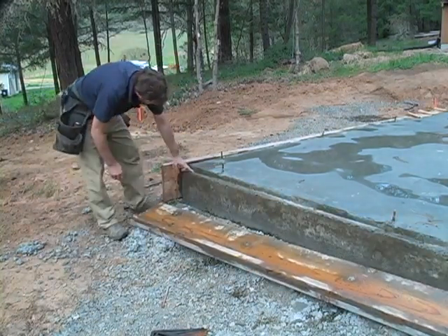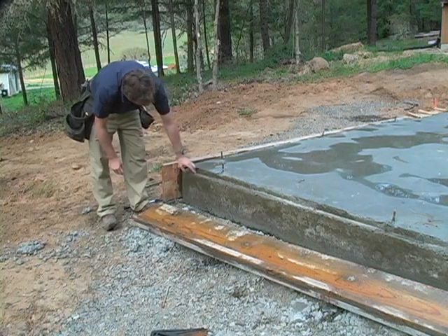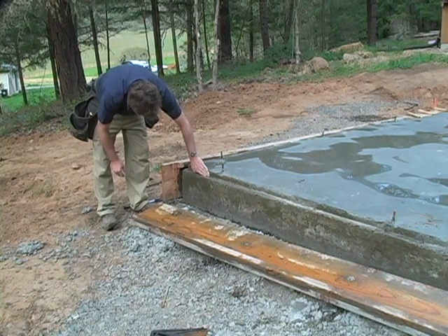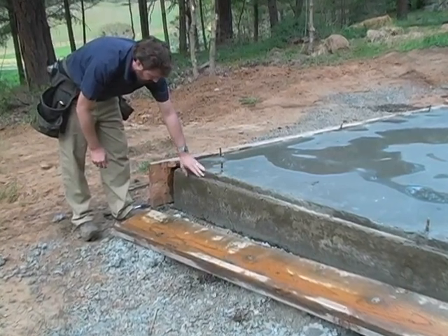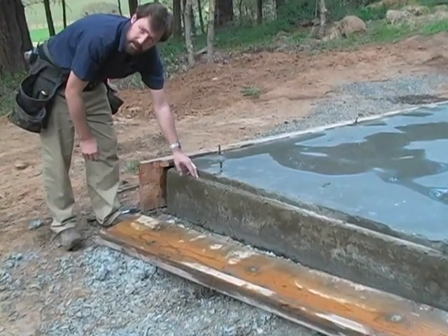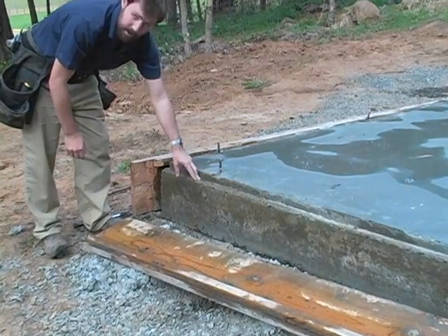So you can see the plaster lip we've got here. This is going to give not just an overlap to stop the wind-driven rains from getting in, but it'll also create a bearing for the plaster, which in this structure we're going to use as a structural plaster skin.